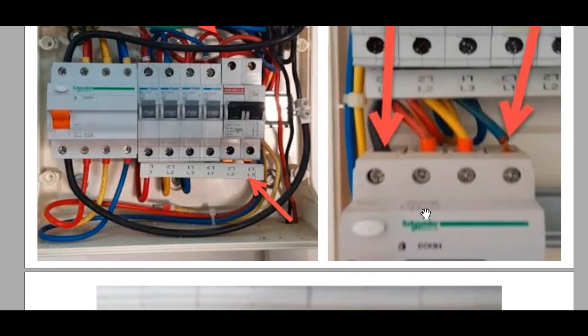So therefore, as you see here, the loop impedance will be changed, and there is no trip. Also there is heat and loose wire, loose connections. Also it is not tripping. So therefore we must select the exact and correct RCD to install in the correct position, to use it for the correct end user.